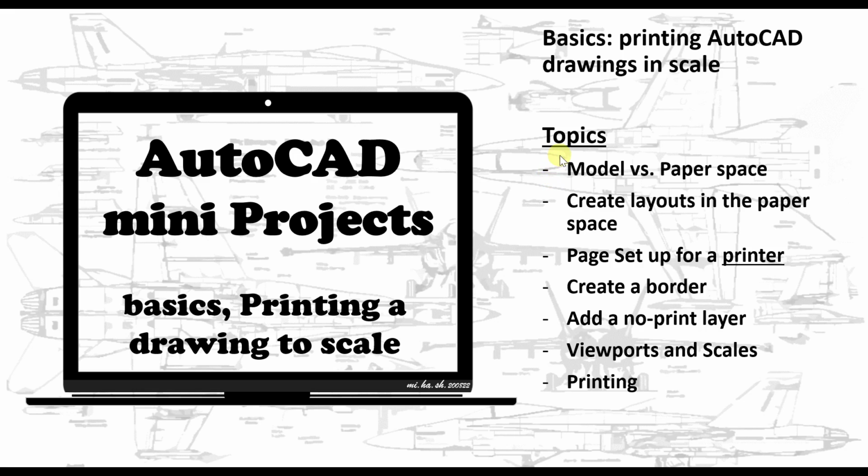So the topics we're going to cover are model versus paper space. There are two spaces in AutoCAD. There is how to create layouts in the paper space, and each layout can have a different page setup for different kinds of printers, or for the same printer but different sheet sizes. So you can set up each layout with a different page setup.